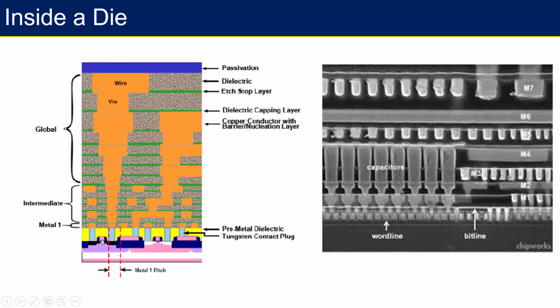This is the metal. Then you see O. Maybe it will be very small here, but you can think of O as this yellow thing also, oxide. Not the gate oxide, but the oxide. You see the gray, the red, the dark blue is also oxide here, which is used for spacer, right? So there are different oxides which you are using. Then there is semiconductor, which is our silicon, right?